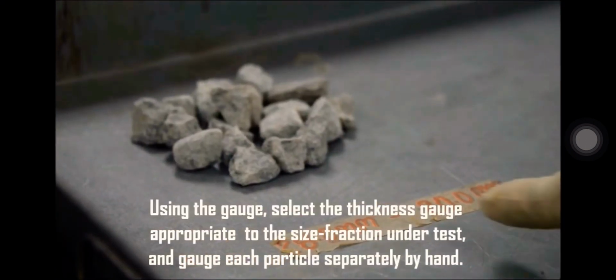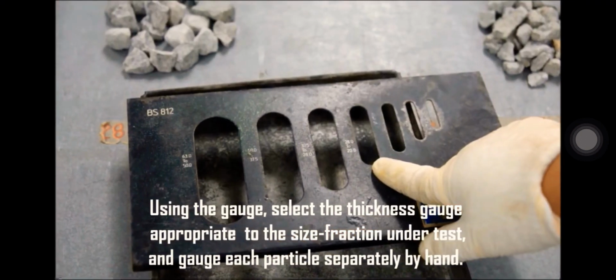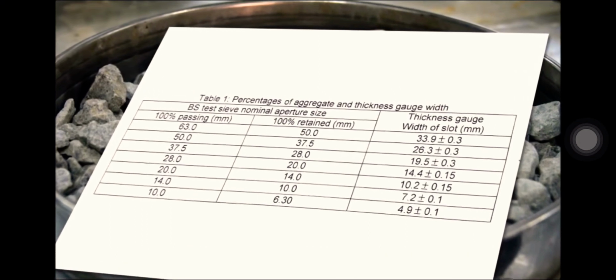Select the thickness gauge appropriate to the size fraction under test and gauge each particle separately by hand. Refer to Table 1 of the Highway Laboratory Test Manual.